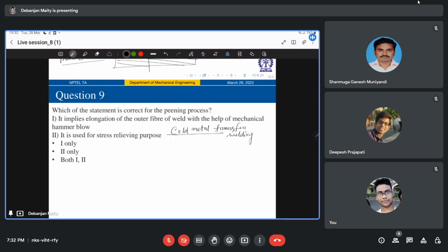So here you can control the heat affected zone or welding zone in a narrow region. Whenever you are narrowing down your heat affected zone, the region where you are getting this columnar kind of dendritic structure will be much smaller compared to some conventional fusion technique. So you can go through this cold metal transfer. You just take a look what it is.